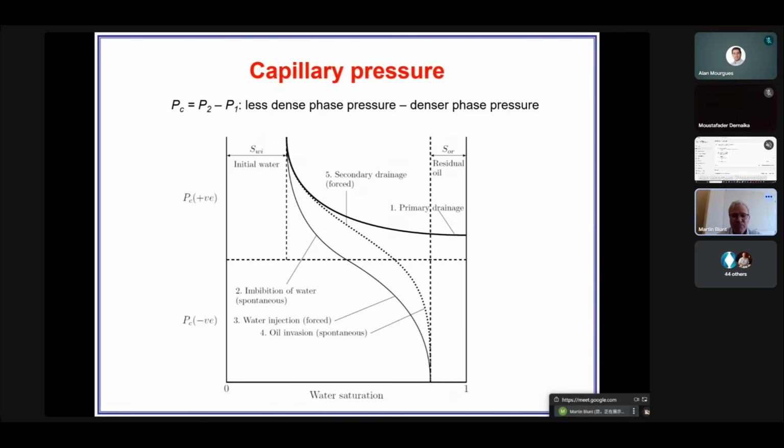Okay, so typically this is what we see in terms of capillary pressure. We don't see capillary pressure as just wetting minus non-wetting with a contact angle, where it's either all positive or potentially all negative, and then you don't really know how to define it. You just define it as the pressure difference between two phases. You accept that it can have both positive and negative regions, and this is typically the type of behavior that you'd expect to see in the subsurface.